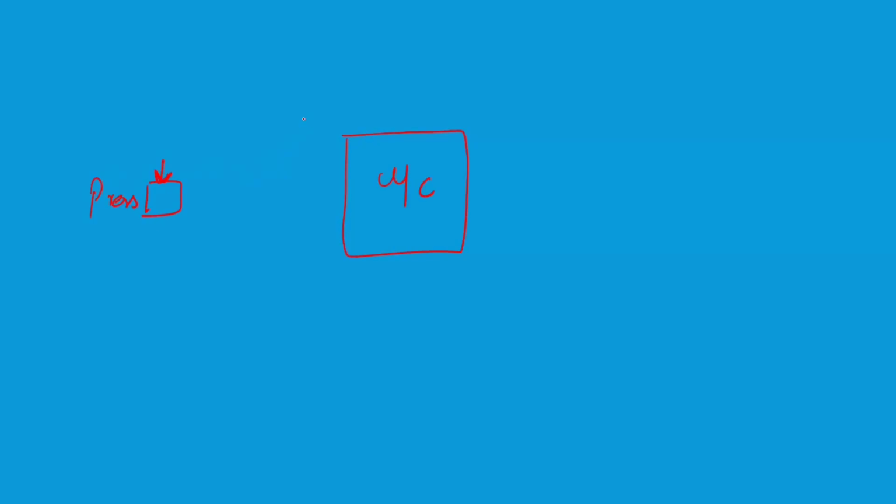You have to define a particular state to your microcontroller, either high, then you press the button, your microcontroller reads 0. So that means previous state was 1. When you press the button, the microcontroller reads 0. So it means a high to low pulse is there.